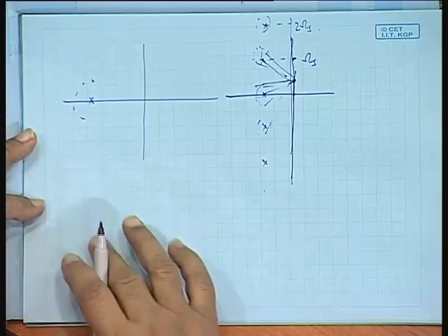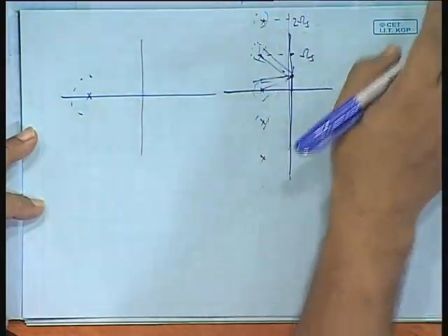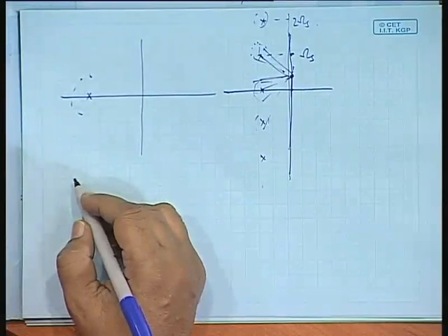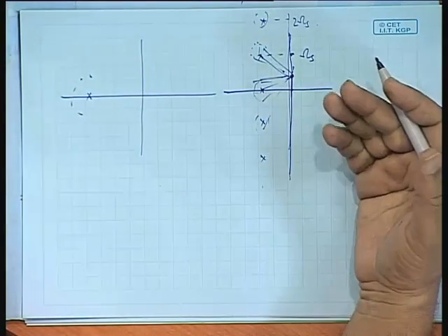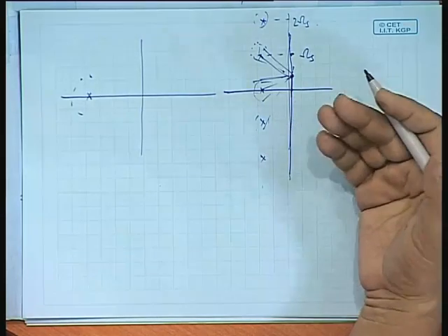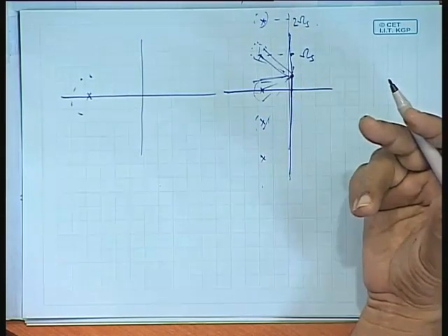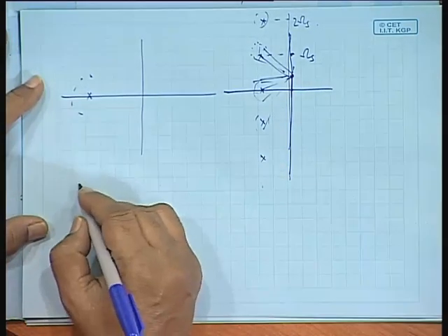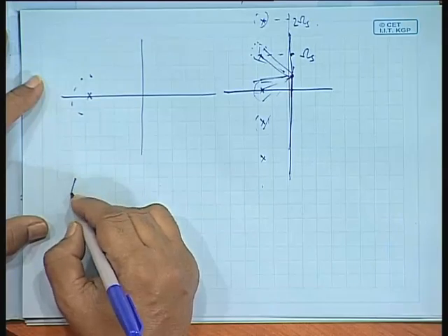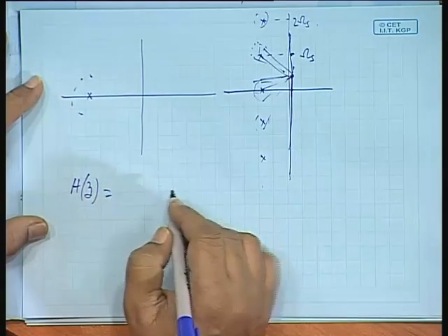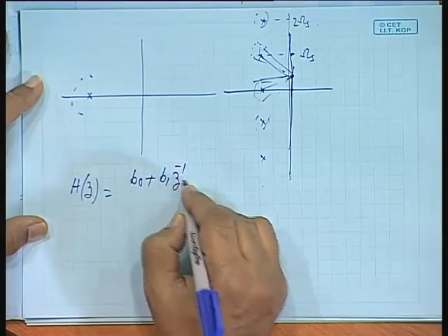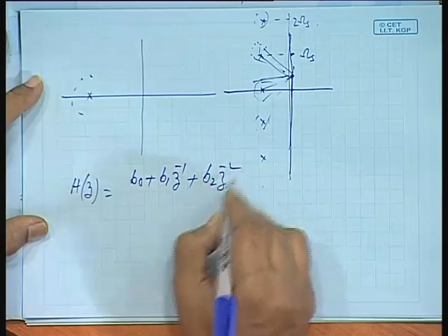Now, we will take up some examples. Before we go, there was one question raised after the class, that is, can we avoid, we are giving examples of impulse invariance and step invariance. For step invariance, we found there are two delay elements, all right. Is it necessary to have two delay elements? So, it is not. So, suppose you have a function say h z, I will take a simple biquad b0 plus b1 z inverse plus b2 z to the power minus 2.